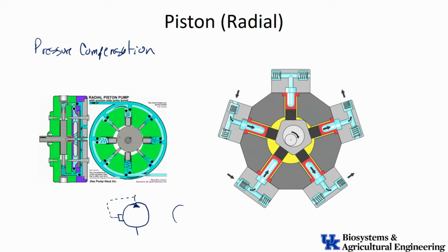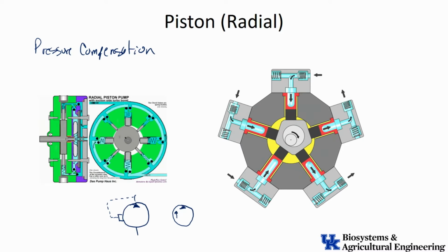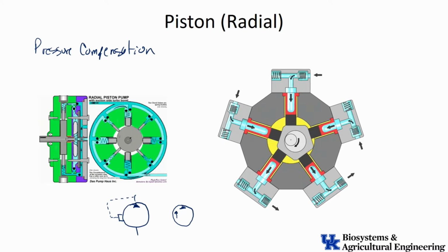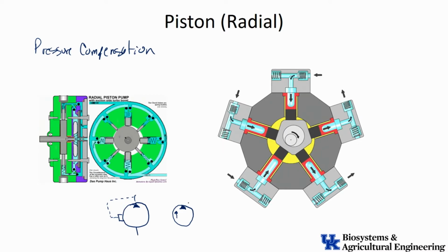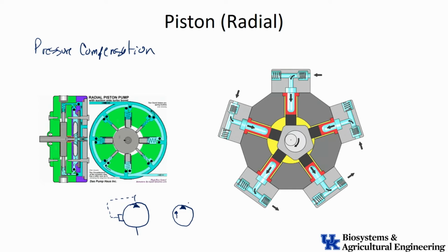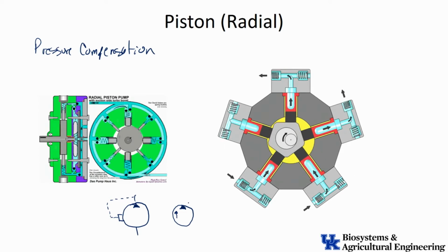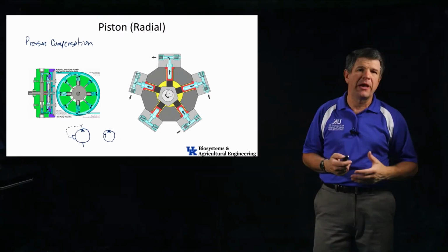And so on more modern drawings and some more modern JIC standards, we'll show a pump like this, with an arrow inside the pump. And again, this small vertical arrow, we'll see that on these types of mechanisms, hydraulic mechanisms, and that indicates that it will act differently depending on what the pressure is in the system somewhere. So a couple of pumps that will de-stroke themselves, and these are the basic mechanisms.